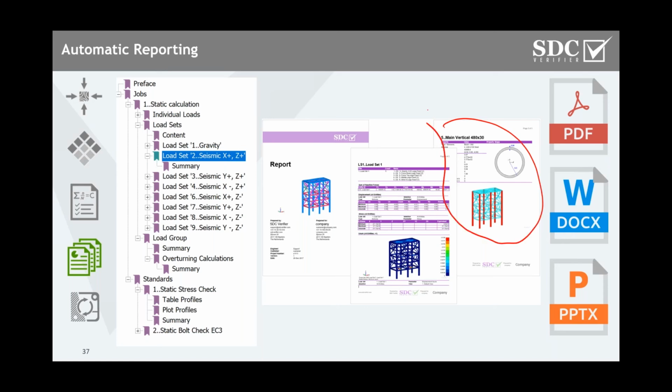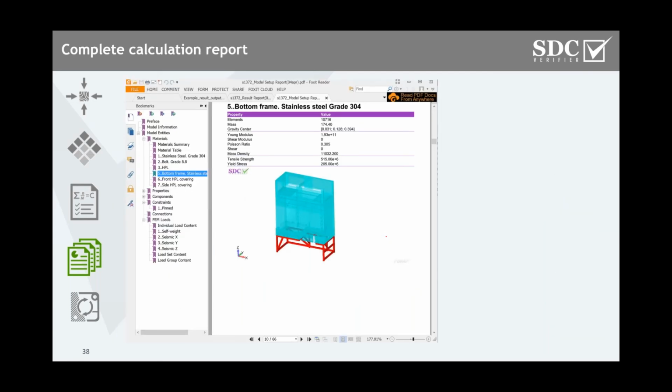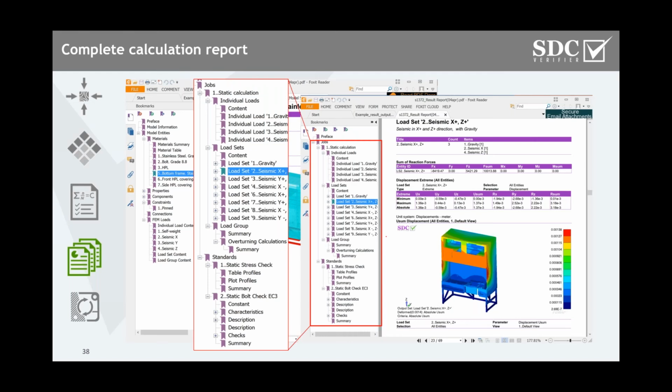And then all the results of your analysis built with nice colored plots and tables explaining each and every combination. They are included in a template-based structure. So you describe how your model is built, you describe all the results, and you follow the same structure for multiple conditions, for multiple loads, and for the complete scenario. And the biggest benefit here is if your model has changed, the only thing you would have to do is go to Femap, recalculate the model, and generate the new report again.